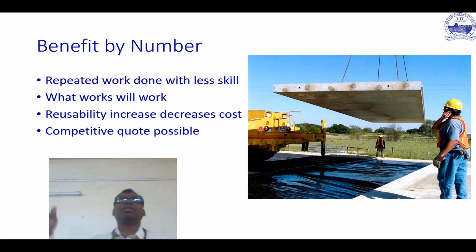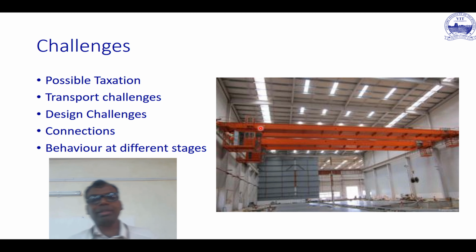What happens is the curve of the road is one of the principal things which determines how long an element can be. You will be seeing a few slides later on where you can actually see the challenge there. And again, the heaviest axle load which can be permitted on a road also needs to be known before you start to send a prestressed precast element.